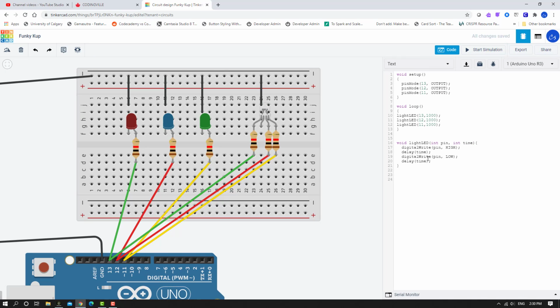to do this. This function turns on a single channel, and while it's good for the purposes of using a single LED, it's not going to work for our RGB LED because we need to turn multiple pins on at the same time if we want to mix color. So we're just going to leave that function there. It's not bad, but we're just not going to use it right now. And we're going to get rid of these function calls.